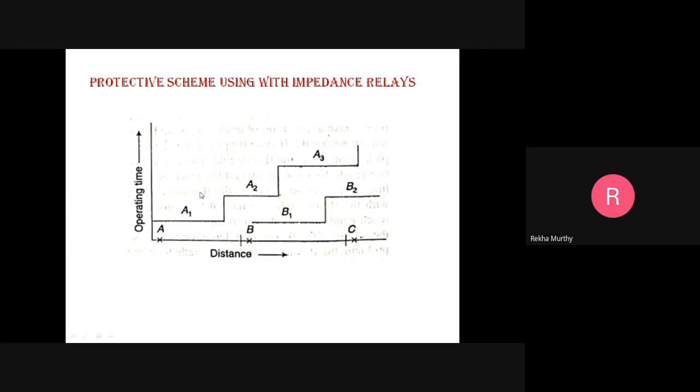The main purpose of the second unit is to protect the rest of the protected line, which is beyond the reach of the first unit. The setting of the second unit is adjusted so that the relay operates even for arcing faults at the end of the line. To achieve this, we must reach beyond the end of the line. Underreach is also caused by intermediate current sources, errors in the data available for the initial setting of the relay, and errors in the CT and VT and measurements performed by the relay.